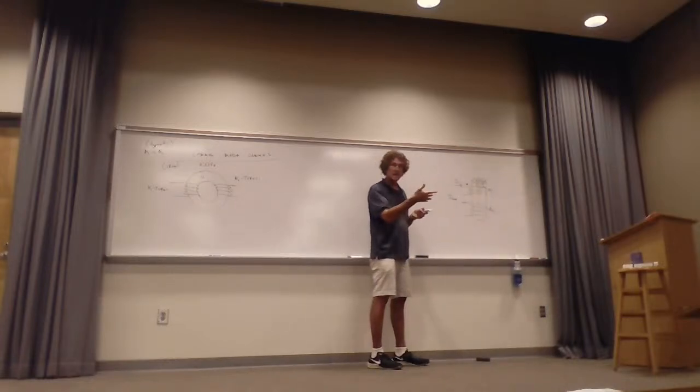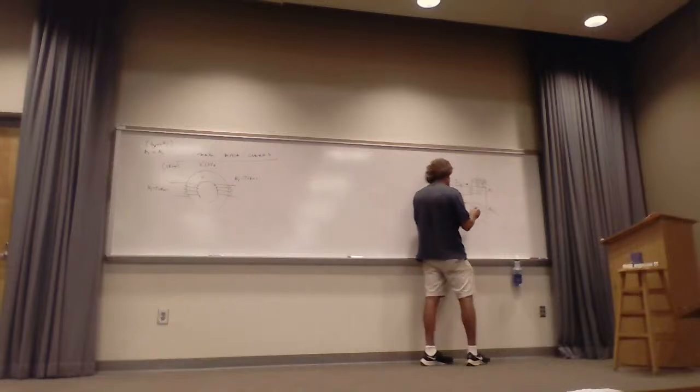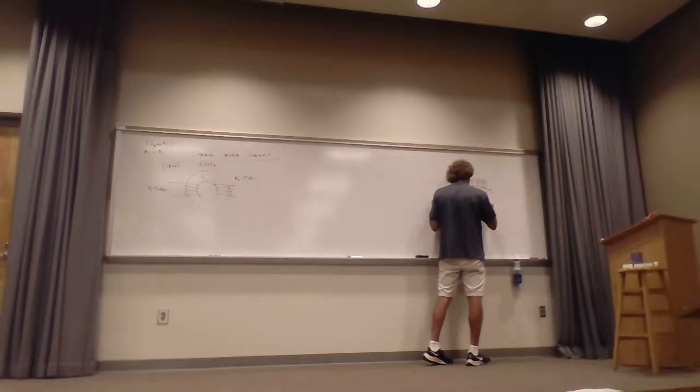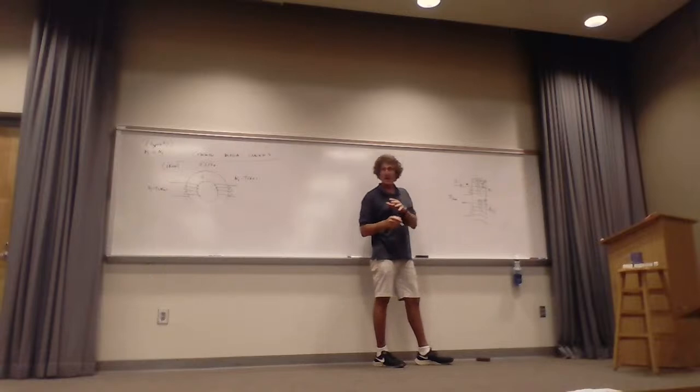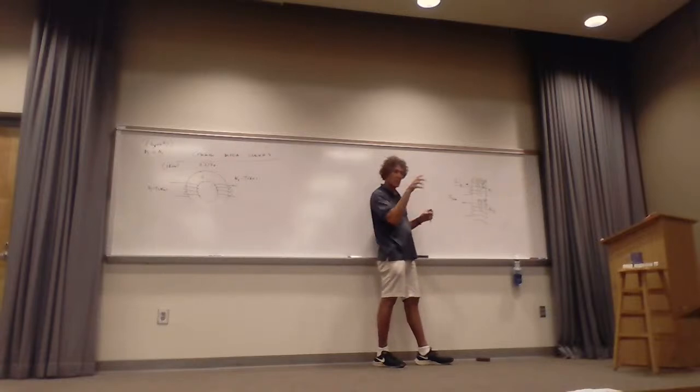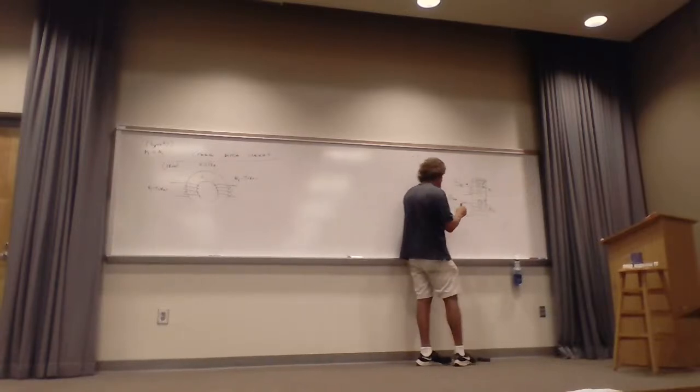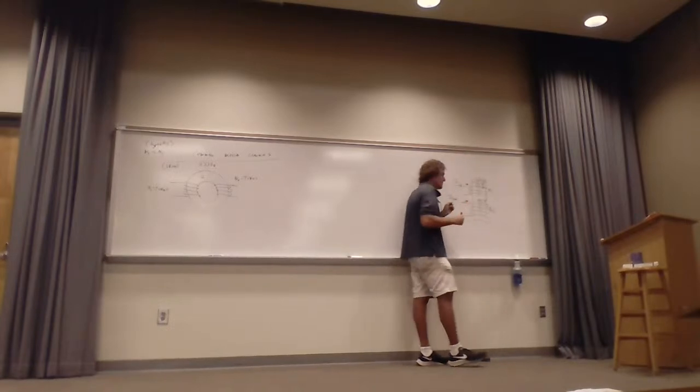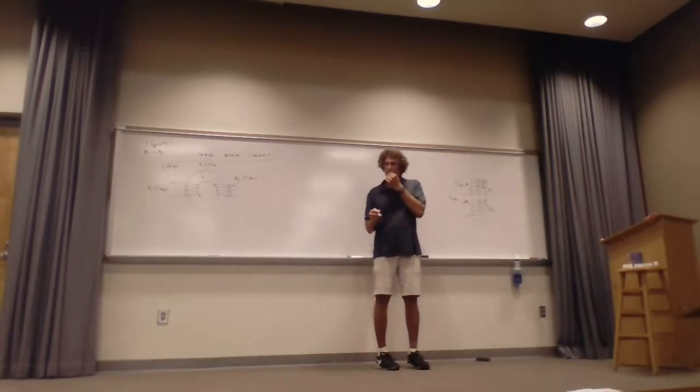If you put an I2 in the second set of coils and the fluxes are in the same direction, in this case they would be, the flux from 2 would be the same as the flux from 1. Do you all agree with that? Because I got the coils wound the same way. Then you put a dot here. This is how you get the dot convention. Now, I'm not going to get the actual inductance, but you all remember doing that, right?